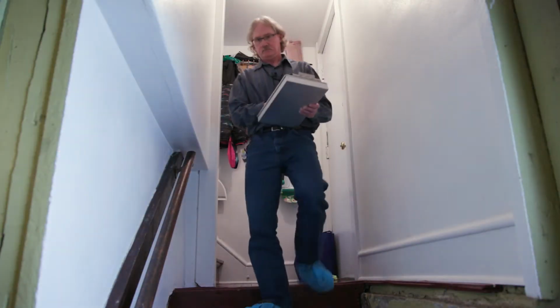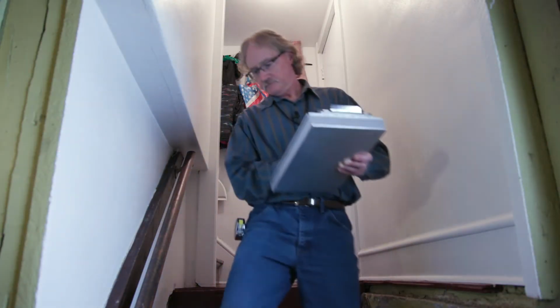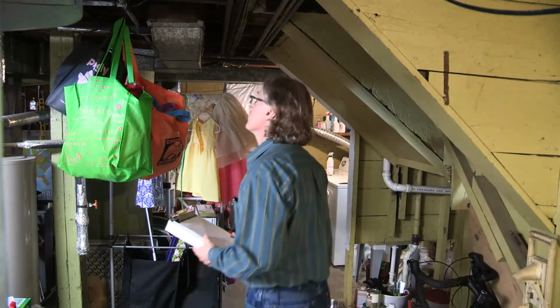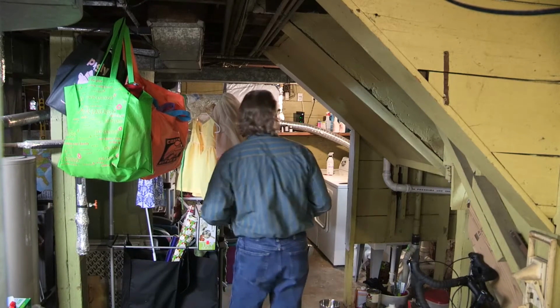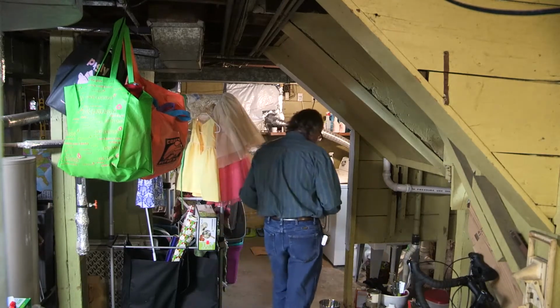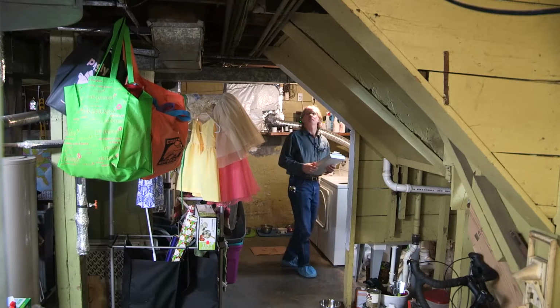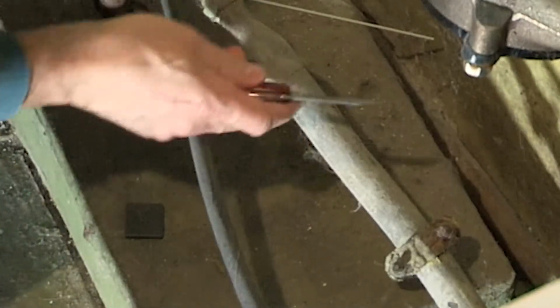Basements are part of the living space and should be assessed. Pay close attention to basement windows, painted floors and walls, and any other painted storage cabinets or shelves. An evaluation of the plumbing system should be done as well. Locate the water service lateral coming into the property and verify it is not a lead service line.